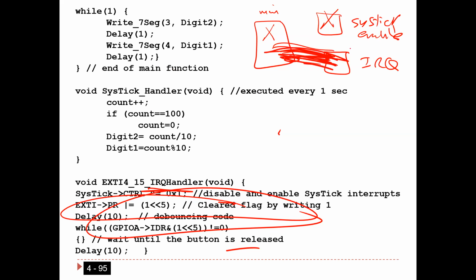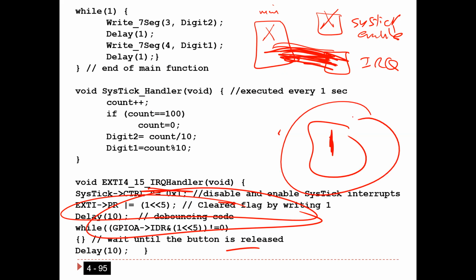I'm going to have continuous interrupts, because once this bit is one, the program will think this is a new interrupt. It's like one interrupt source continuously requesting an interrupt because you forgot this one. You get what I'm saying? So what you should see in the video is that this task is not going to run with time multiplexing, and also the count increment is not going to work, because all the time we're going to be here. I'm going to choose a video and then I'm going to take the question there.